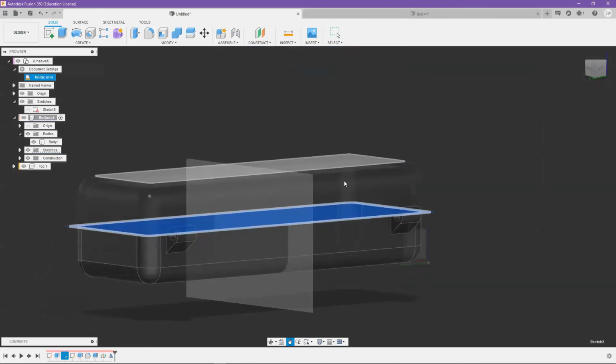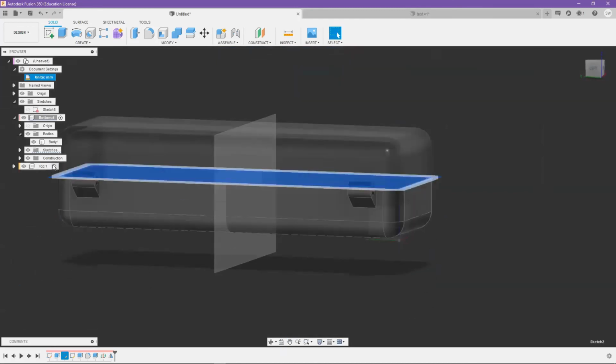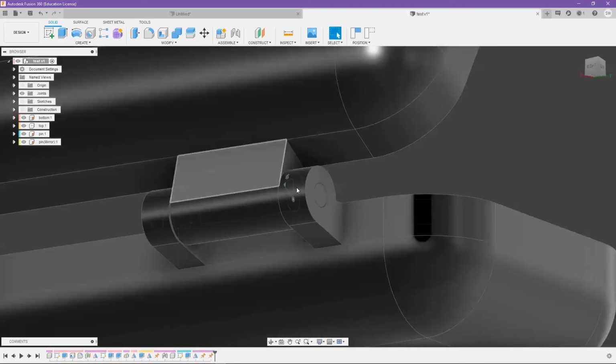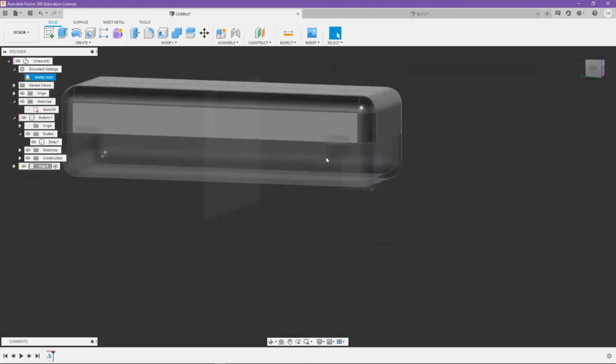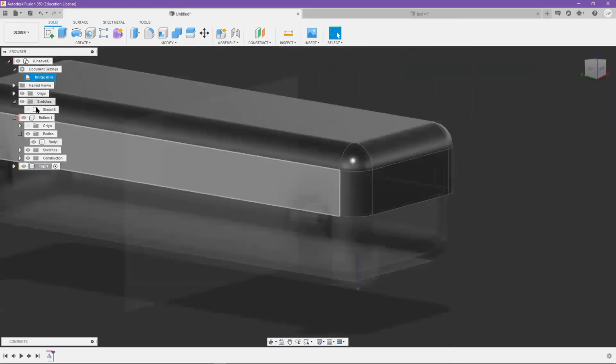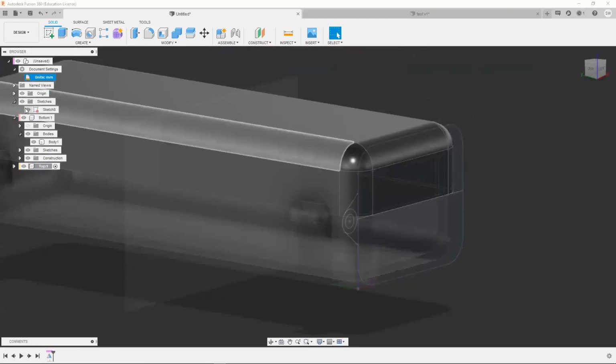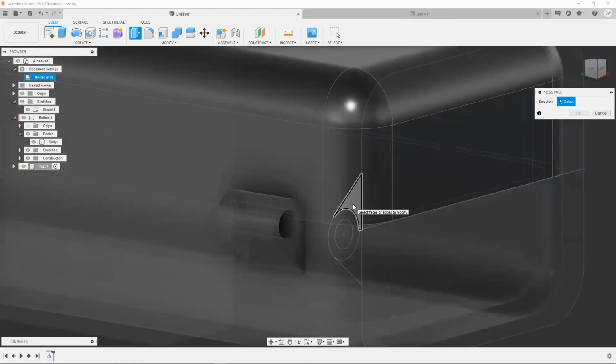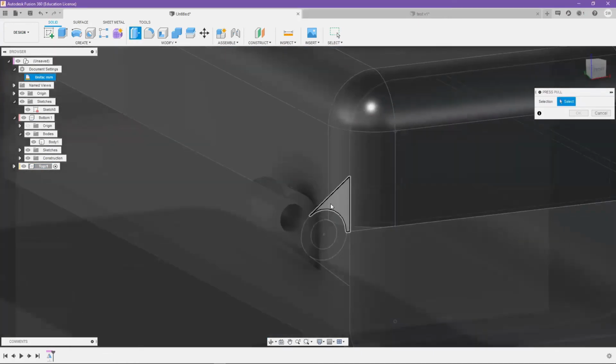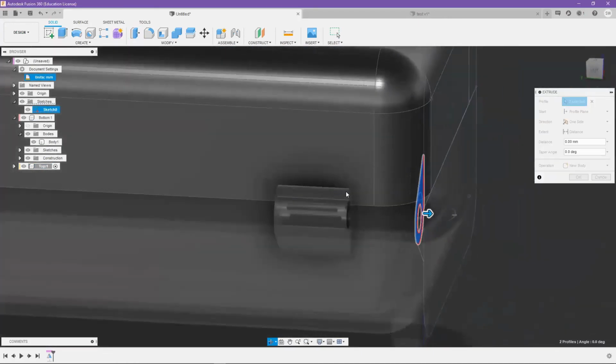It's pretty cool. Yeah, so now I'm going to go back to the top here and finish creating the top hinge. So since this is from the bottom, I'm just going to create these 2 little things. And it's the same thing. You have to make sure this is not hidden. The sketch is hidden by default when you create something on it. Fusion thinks you're done with it, so it just hides it. But for this top part, I need these 2 profiles.